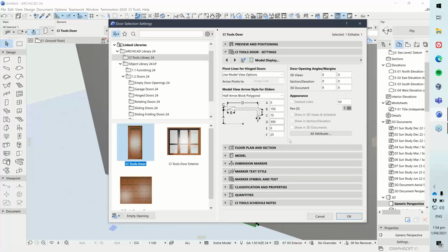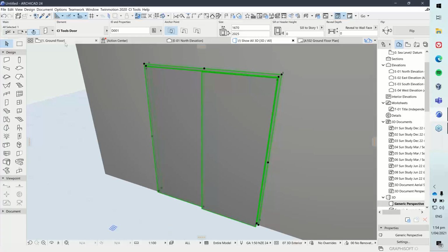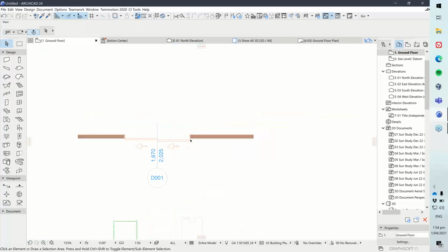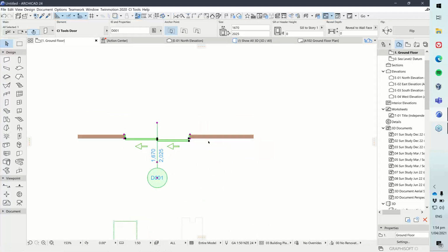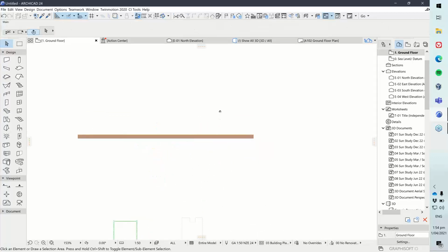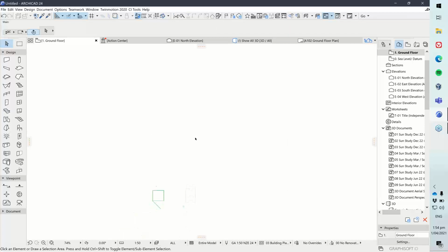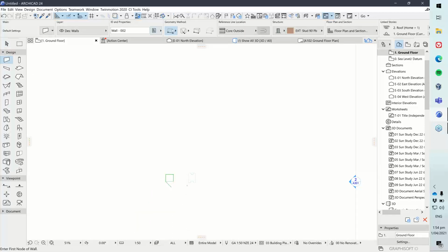So that's just showing the arrows on your sliders. Now, the last thing I want to do before we finish up and look at some questions is to very quickly look at drawing up corner windows. It's something that I've had people ask about recently, and I'm not sure if it's something that people generally know that you can actually do using the Doors and Windows tool. So I'm just going to very quickly draw up a corner window so you can see how to do it.